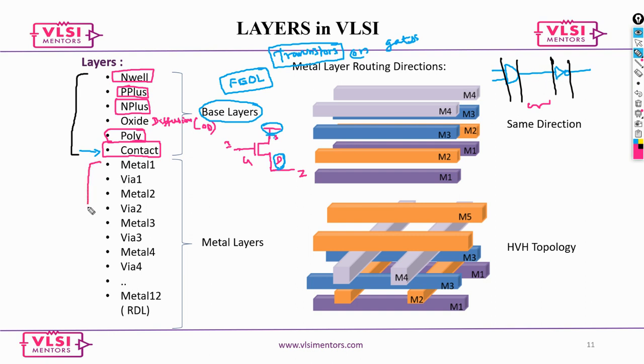So you use metal layers. Now remember, these are all base layers which involve different impurity addition and all of that, and we use metals to manufacture your nets, so that your R and C values will be lesser. That will bring down your net delay.